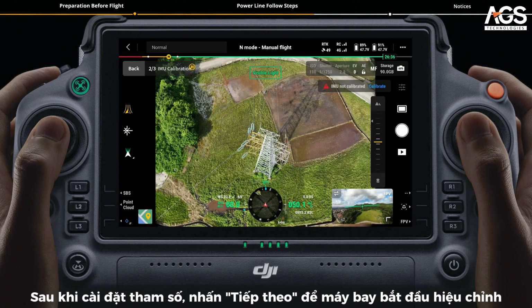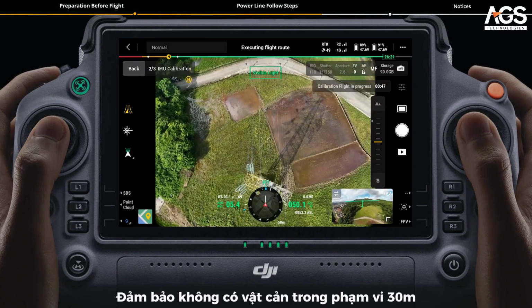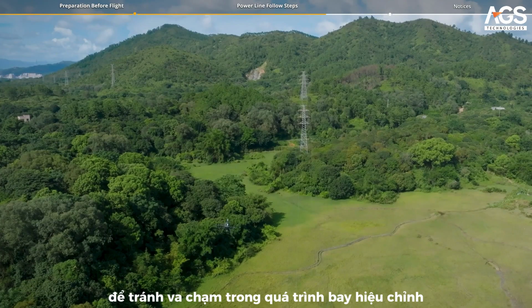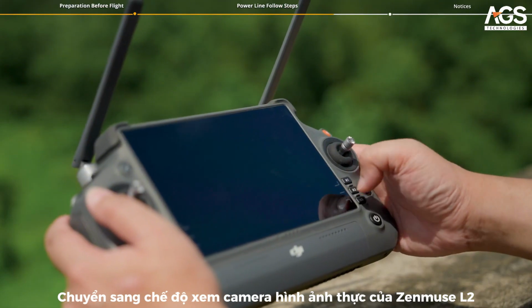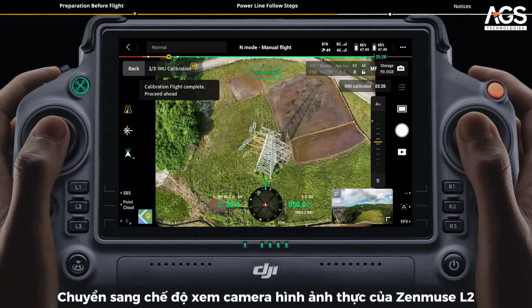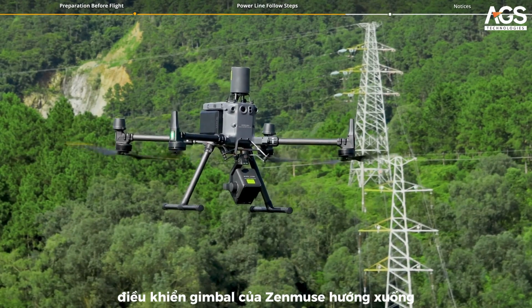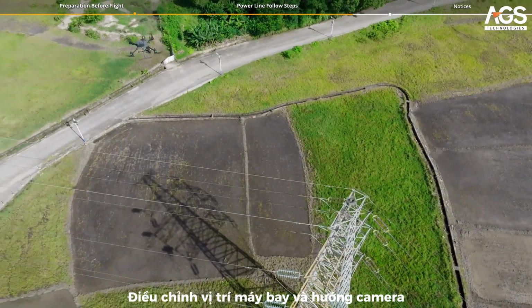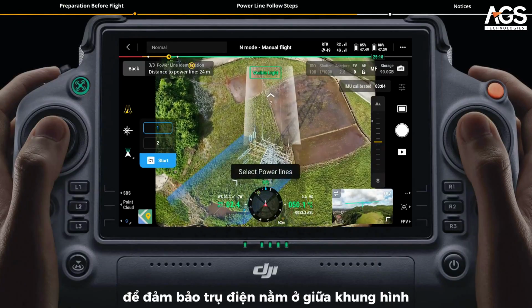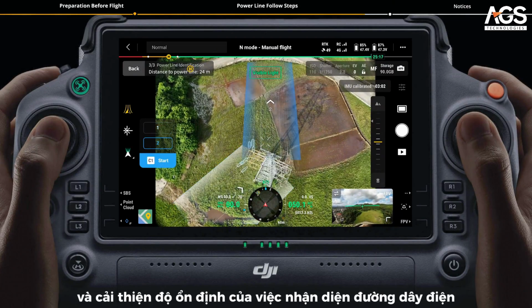The aircraft will start calibration flight. Make sure there are no obstacles within a 30-meter range. To avoid colliding with obstacles during calibration flight, switch to the Zenmuse L2 visible light camera view. Control the Zenmuse L2 camera to tilt downward. Adjust the aircraft hovering position and camera orientation to ensure that the electric tower is centered in the camera view and improve the stability of line identification.